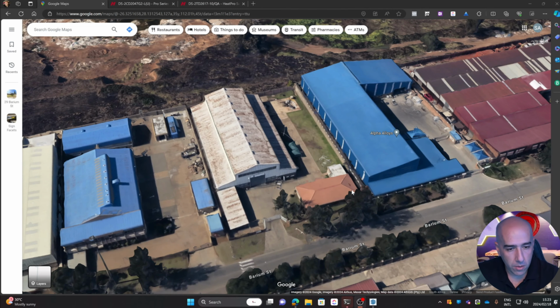The first thing we've got to do is open up Google Maps, find your site. I highly recommend that you visit, walk around, take photos, record as much information as possible, so you don't have to go back to the place. That's the worst thing, when we remember that I forgot to check this area out, now I don't see, because Google will not show everything. We need to go to site and see it.